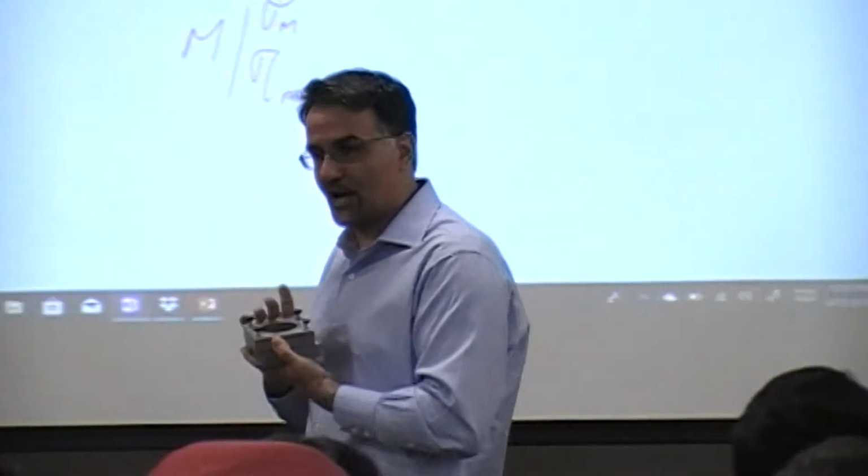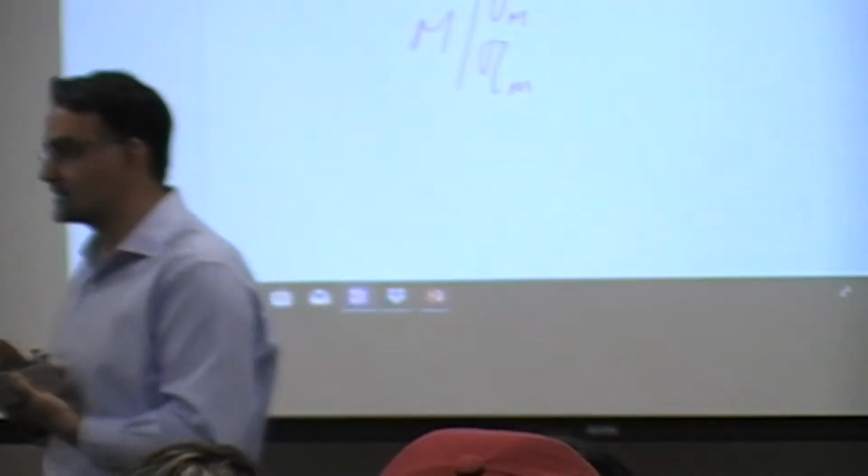It's right here. I'm sliding it right past one another, therefore the failure plane is going to be predetermined. It's going to be along the horizontal line. Do you agree? Is it going to happen in diagonal? Probably not. And that's exactly the disadvantage of this type of test, because in reality, we know that our soils are not going to fail in a horizontal plane. They're going to fail in a diagonal plane.